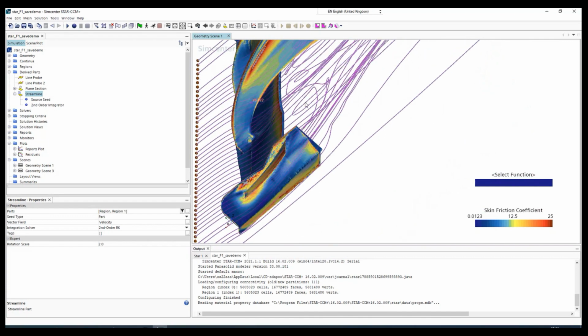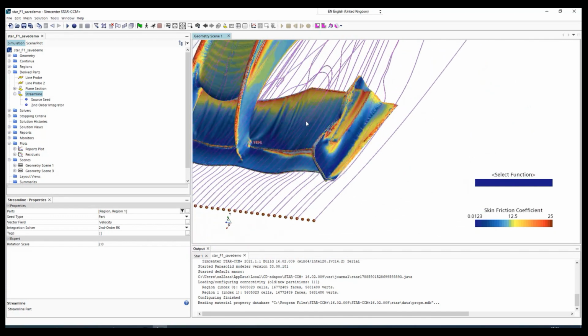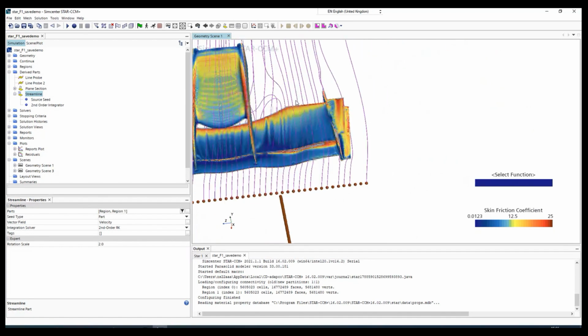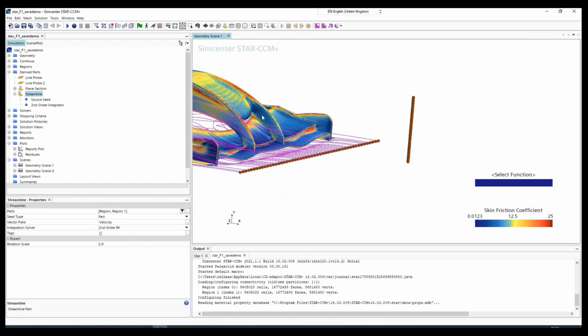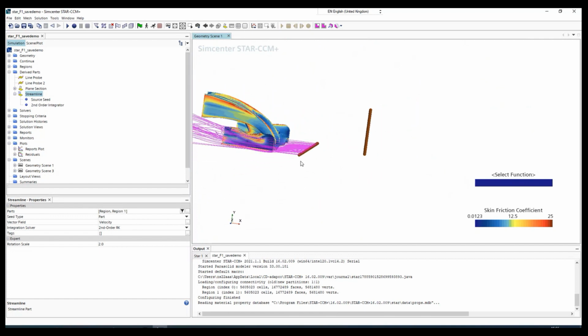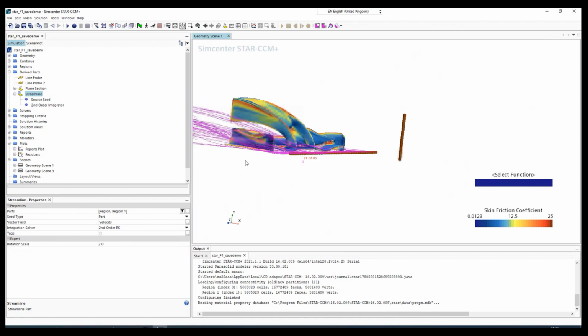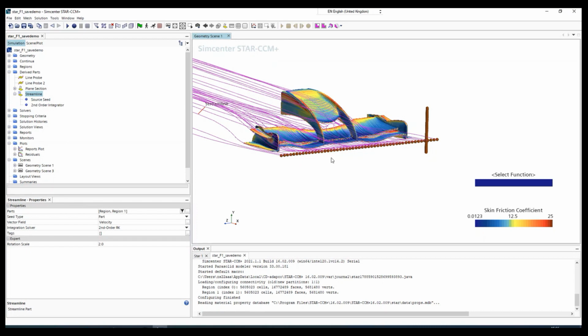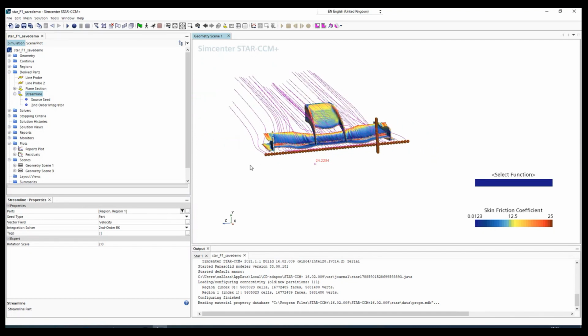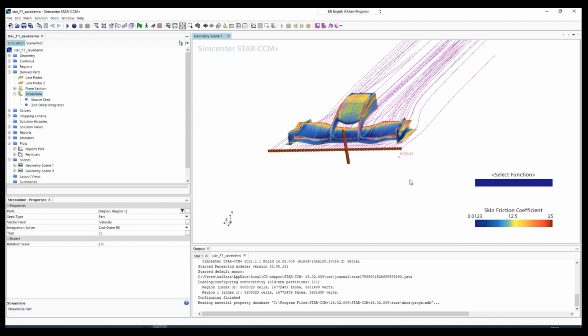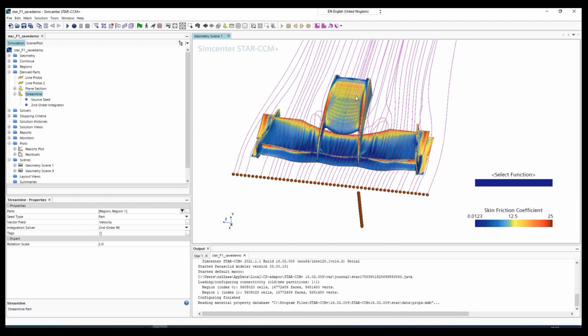Yeah. And this is also a very important skill to study the flow field. Okay, so in this part, we visualized the vectors within a plane and also the streamlines through a seeding line. These are the two important skills for post-processing and how you interpret your data. And if you are an aerodynamic engineer, you perhaps want to remove this or improve the flow separation. And through the streamlines, you can see how it is improved.